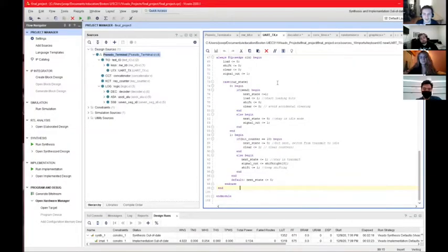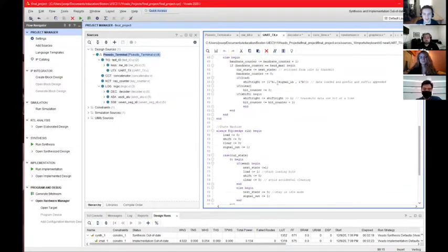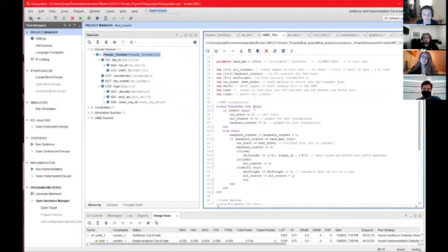All right, I'm Jack. I wrote the main code for the UART transmitter. The two main modules contained within this are the module that controls the baud rate counter, that tells the terminal that the UART is talking to the width of each pulse that's being sent. It basically takes the clock speed of the FPGA and divides it by the desired baud rate, which in this case is 9600, and it will count up to that value and send the bits one at a time from there.